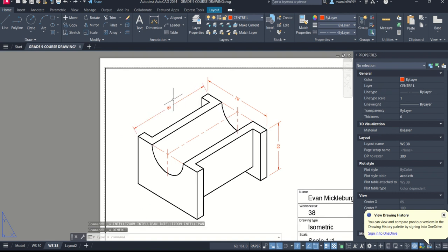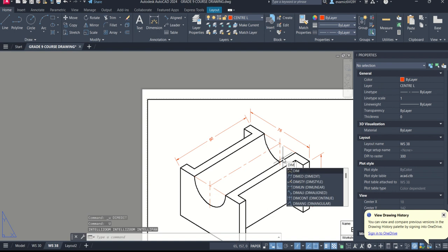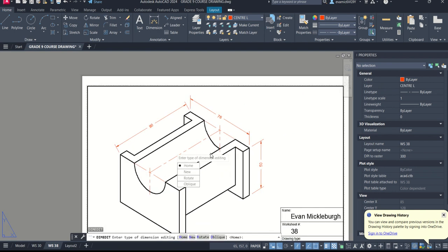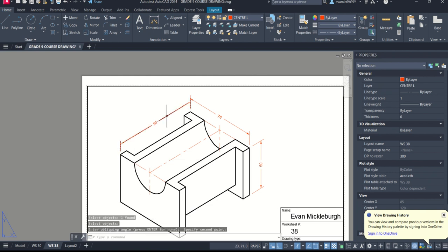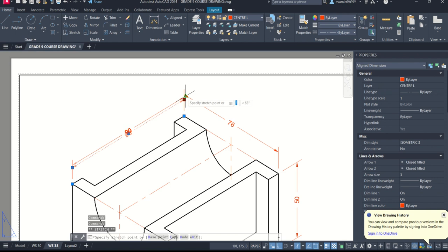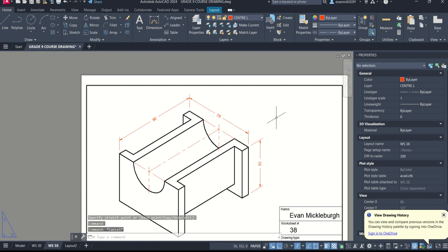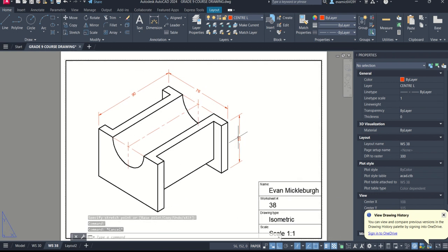you can go back and go dim edit. Let's see, it might just look a little bit better. So we oblique it, click on it, and then obviously I want it to then align with that. Right, and then if you need to, you can pull it to the same point. Right, there we go. So everything is in place. The measurements are in place. Looks good, ready for saving.